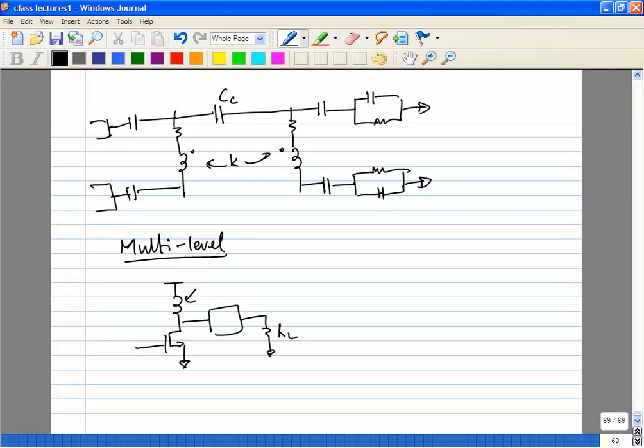What you're actually using it for is, you're trying to make sure that, what property of the inductor do you know about? It doesn't allow current to change suddenly. So if you have a very large inductor, it tends to have the same current. So effectively what this is doing is offering a DC bias. It's biasing the output at VDD, but it is also keeping the current through itself stable. So most of the biasing current flows through this, most of the signal current flows through the output. Yes, that's the reason why.